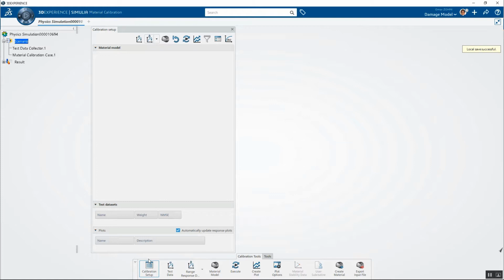Typically the material models are linear elastic, elastic plastic, hyperelastic, viscoelastic. There's also a really nice hyperfoam model and a viscoplastic model, but for the most part, customers coming from the SolidWorks world into SIMULIAworks are probably going to be in the elastic plastic, hyperelastic, maybe foam, maybe viscoelastic range.